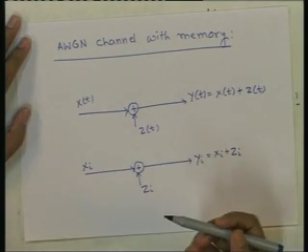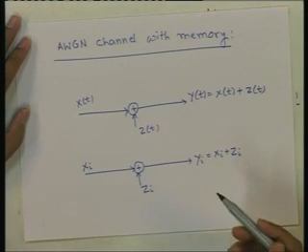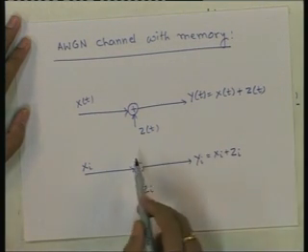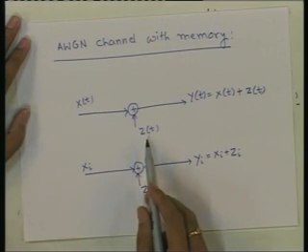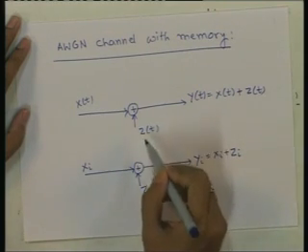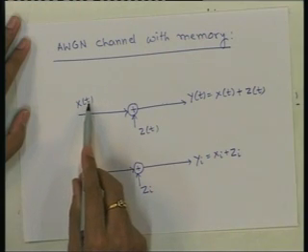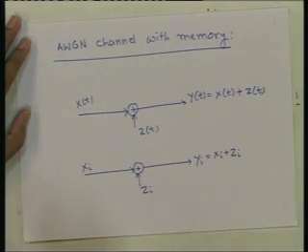So, their power spectral density need not be flat in the frequency domain, and as a result there is correlation in the time domain in the noise. So, what happens to the transmitted signal at time instance t depends on what happened to the signal values in the past, because the noise values at t are correlated with the noise values in the past.